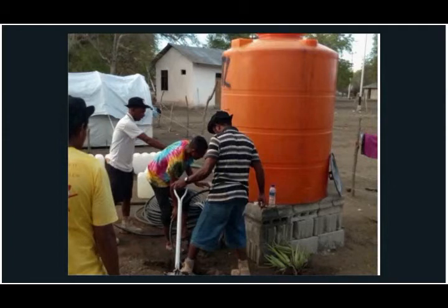Usually the most common one is called a water level dip meter, which is basically a sensor on a tape measure that is lowered into a borehole. When the sensor hits the water, it beeps, and you can measure the distance or the depth of the sensor. We use this often when we're doing pumping tests as well, to help with the assessment of the aquifer.